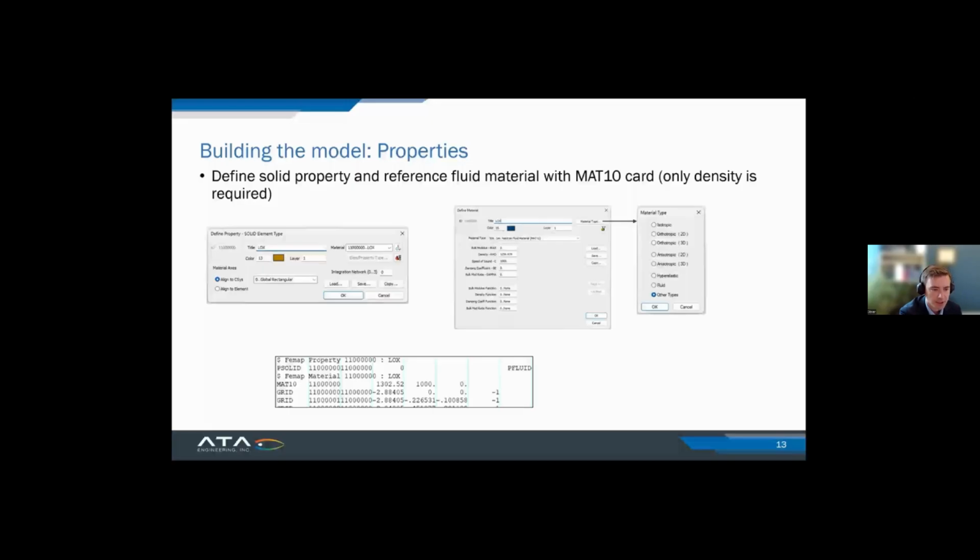What you're then in the end left with is this Nastran PSOLID property that has this PFLUID. And then, like I said, all the individual grid points that refer to this mesh have the output coordinate system of -1, which tells Nastran this is a fluid point.